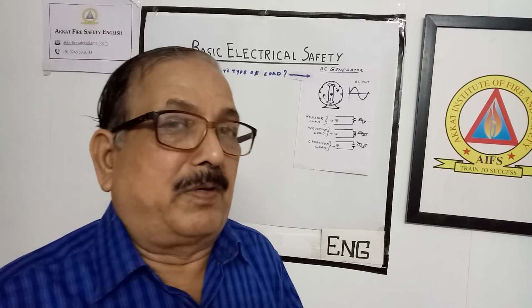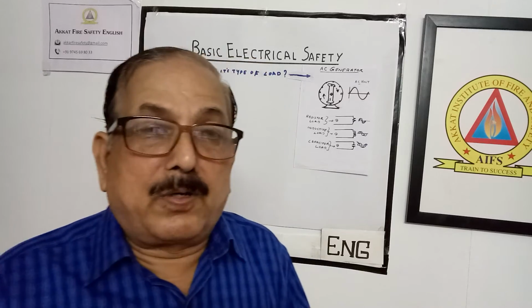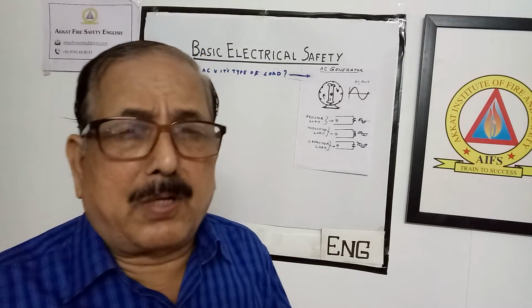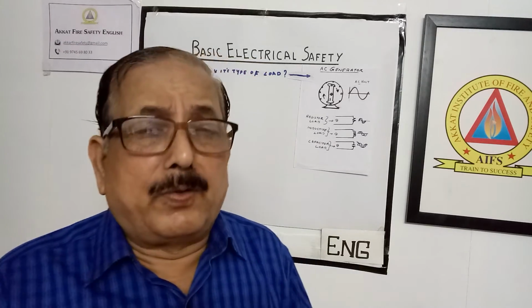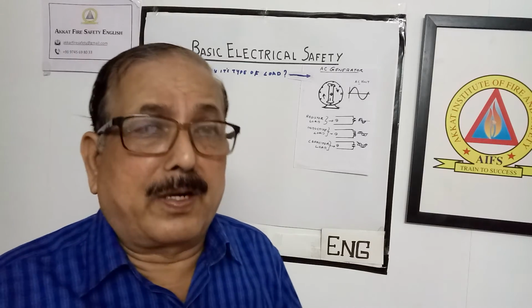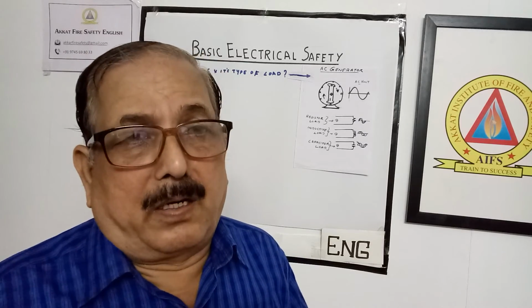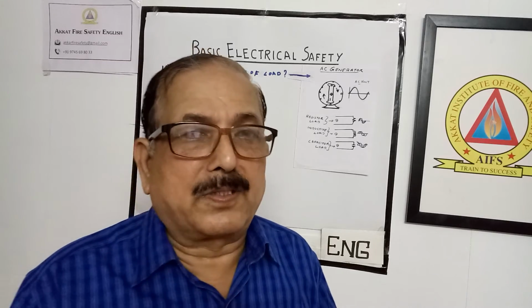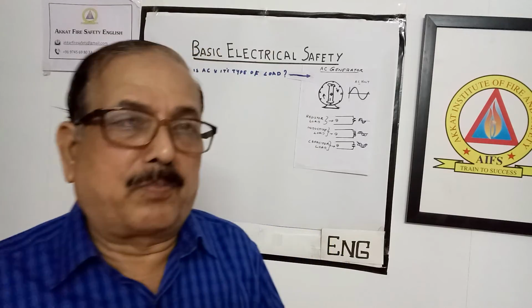So leading current, we can say that. Most of the loads are inductive type loads. In order to improve the power factor, we are giving additional capacitors in the circuit. So this is the basic idea of the AC.